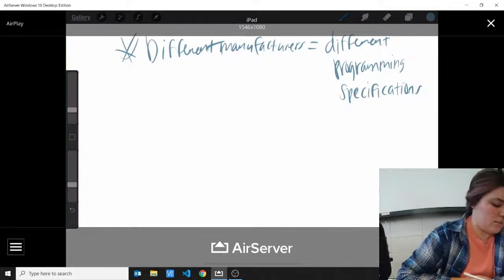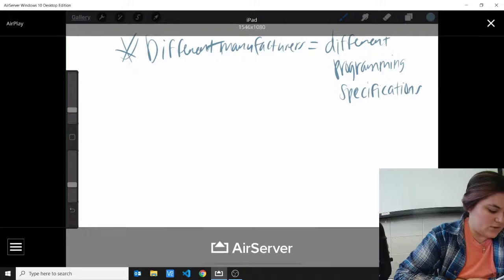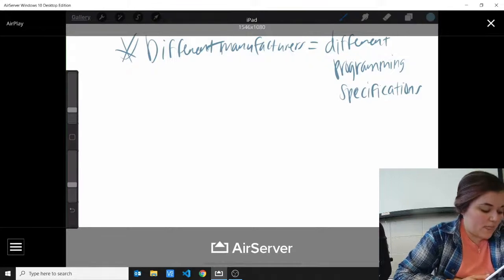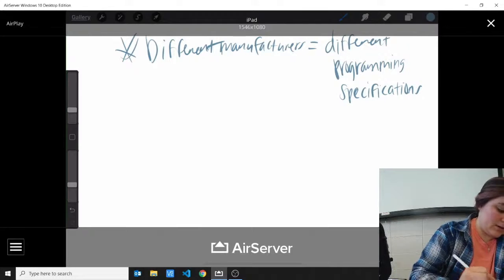And then input devices are either normally open or normally closed. You know that from PLCs. The normally open devices are referred to as examined if closed, and that stands for XIC. I'm sure you remember that too. And the normally closed devices are referred to as examined if open. Let me just write that down, just so it can give me a refresher too.